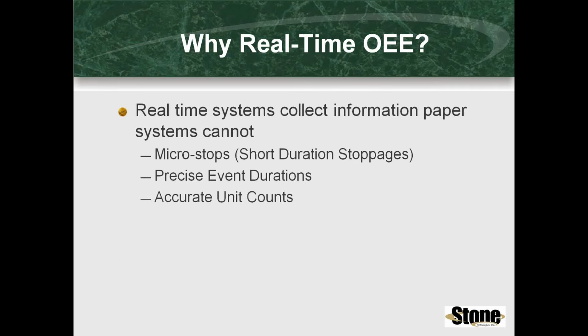So why real-time OEE? Why is this so important? Real-time systems collect information that paper systems cannot. Think about micro-stops. A 2-second stop rarely does someone remember that at the end of the shift. A 10-minute stop, they remember. But what if that 2-second stop happens 25 times or 500 times throughout a shift? Those add up to be impacting your overall performance.